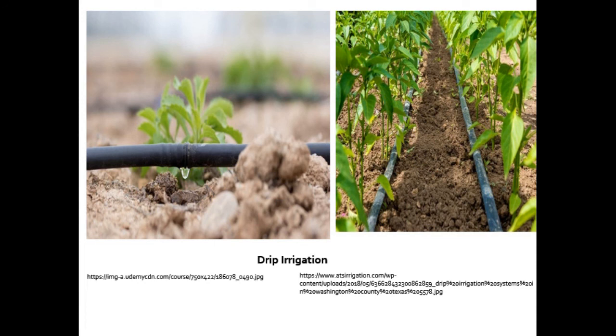Likewise, it is not suitable for very closely seeded crops such as carrots and radishes. Furthermore, initial cost can be more than an overhead system. Likewise, the sun can affect the tubes used for drip irrigation, shortening their usable life. Likewise, a drip irrigation system cannot be used for damage control by night frost.